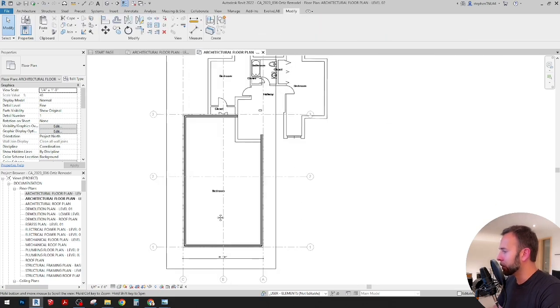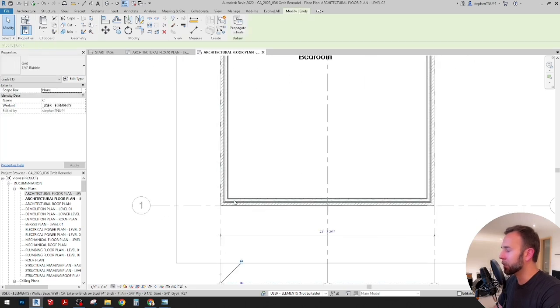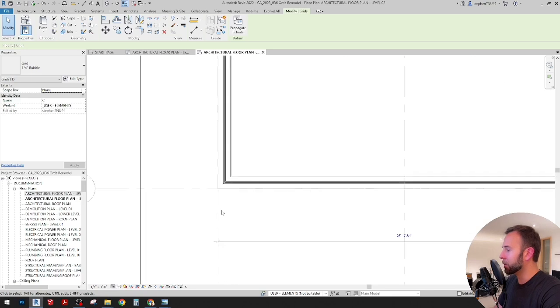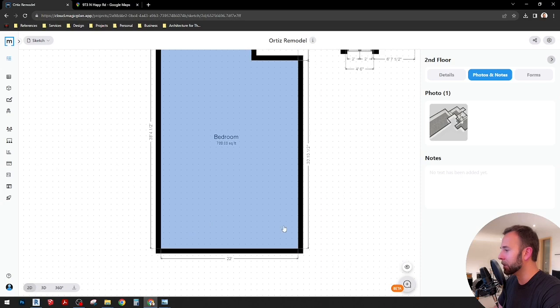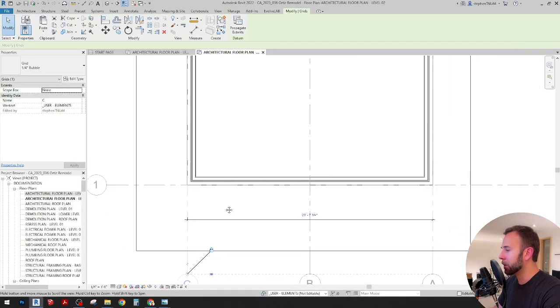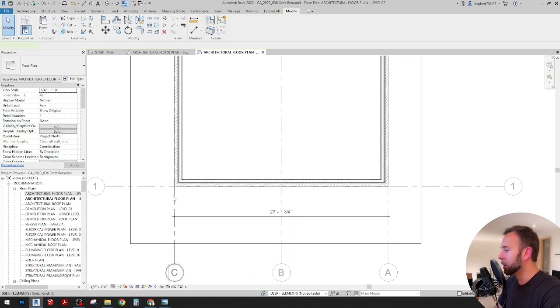So something else I just remembered to keep in mind is the survey dimensions. If you're doing interior survey, you have to remember those are interior to interior wall dimensions. So the grid lines that you place down may be aligning with the assumed exterior walls that your programs are assigning or you have assigned in your surveying program. So in this case, I do have a certain dimension that I surveyed, which was 22 feet from the inside to inside at the base of the roof line in the attic space. So I want to just come in and make sure that that dimension is actually set to 22 feet.